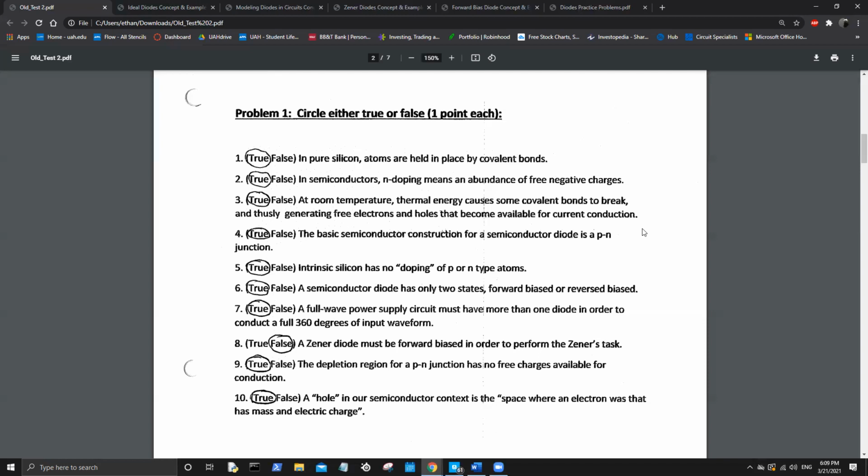As you increase the temperature in pure silicon, which is traditionally garbage at conducting electricity, you will slowly create more free carriers, that being electrons. Then you can slowly start to conduct more charge, which is interesting because if you heat up metal, you lose the ability to conduct charge as your resistivity increases. But in semiconductors, heat normally results in an increase of free charges, which is why thermal throttling is a thing. Cool.